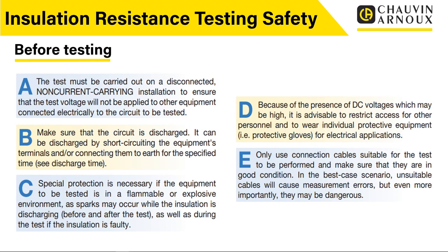D, because of the presence of DC voltages which may be high, it's advisable to restrict access for other personnel and to wear individual protective equipment, i.e. protective gloves, for electrical applications. So yeah, just think about your PPE in this case. You'll often see in many pictures of people carrying out these types of tests that they are wearing insulating rubber gloves.